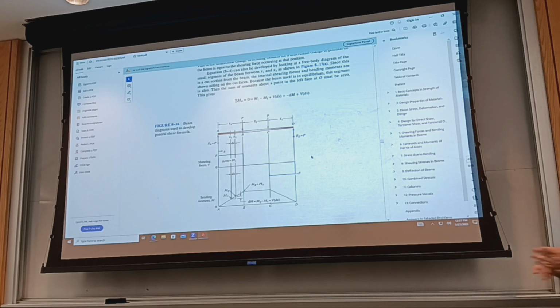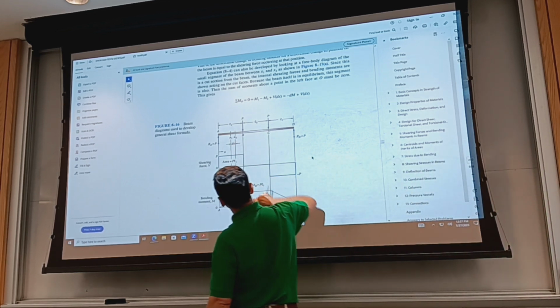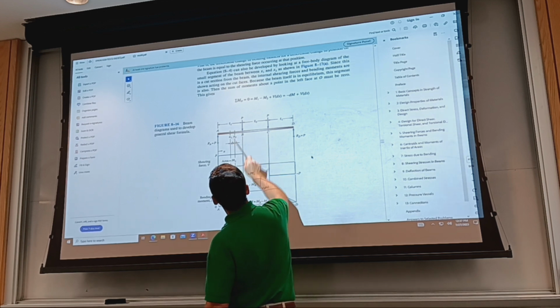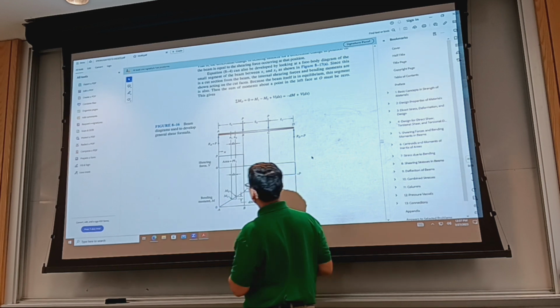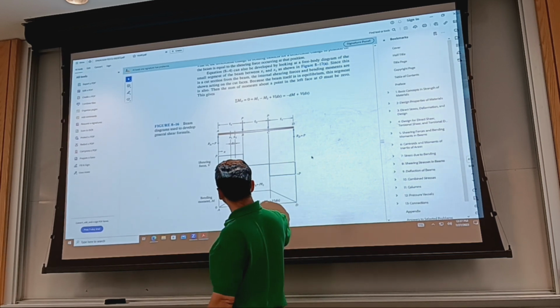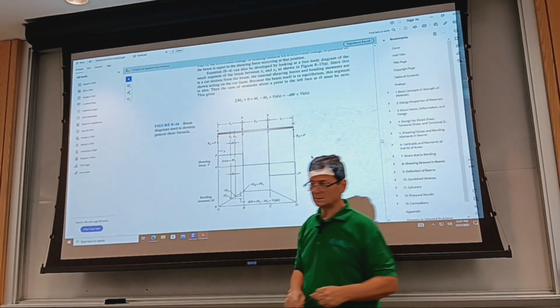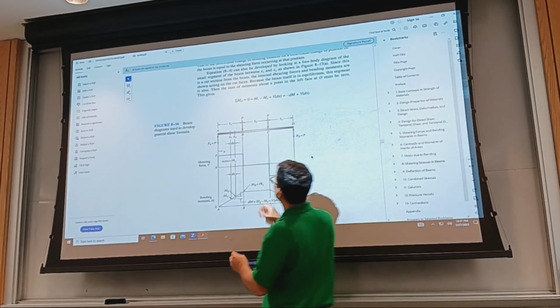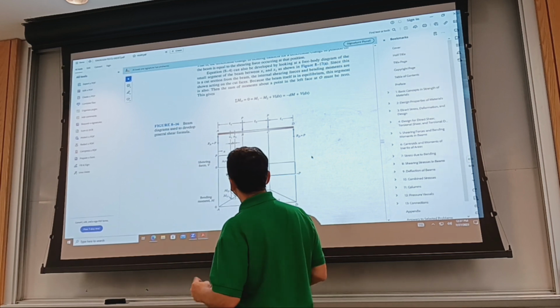So say you're here at x1, and then you move dx to the right. This will delimit the slice of the beam, and we have two moments, M1 and M2, left and right of the sections of that dx.